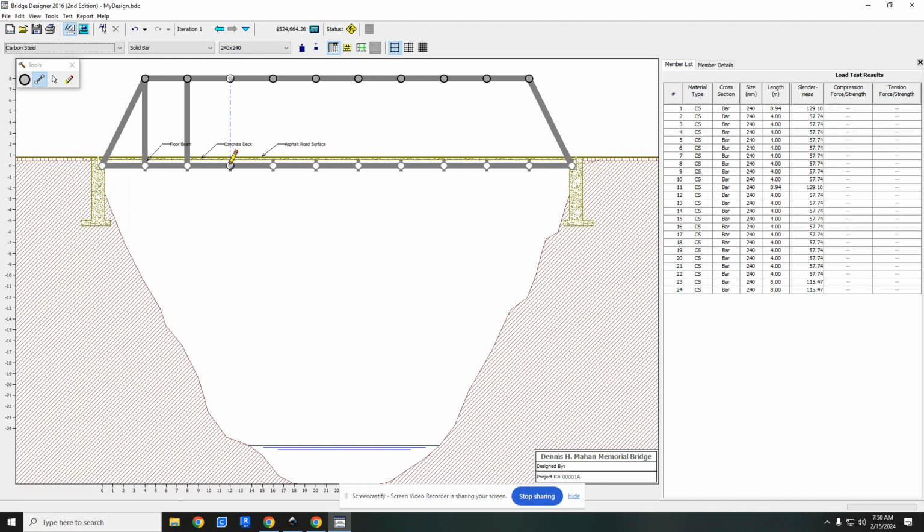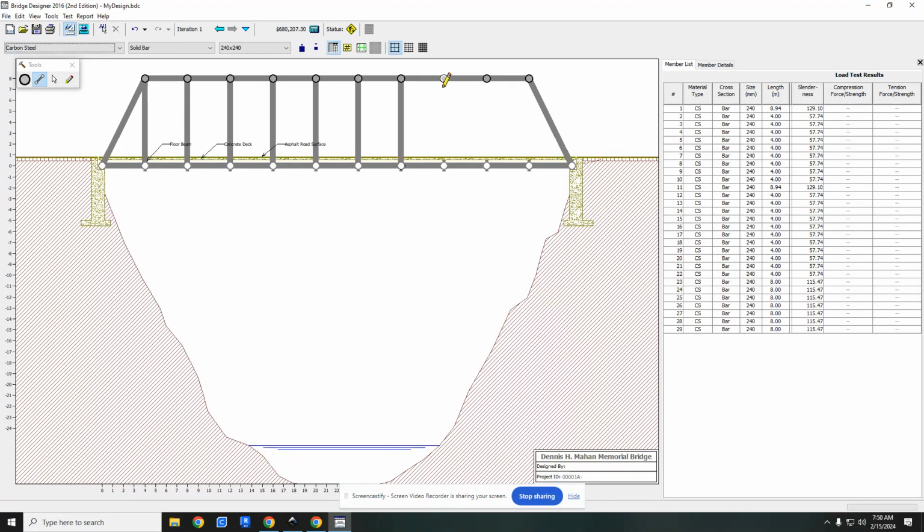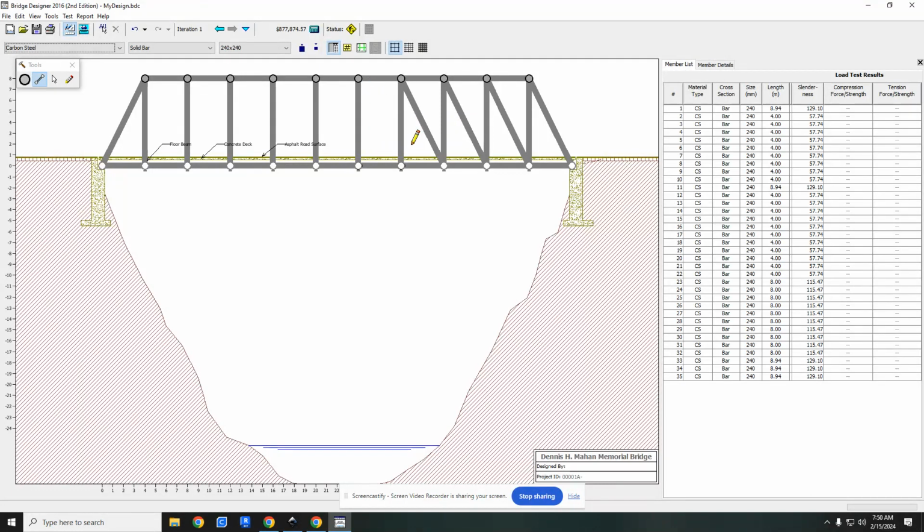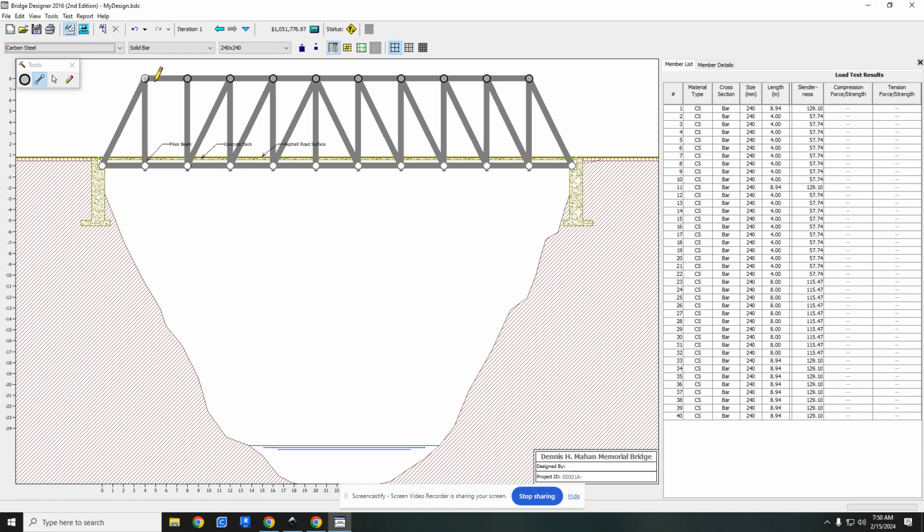Now, remember in the presentation that I have posted on bridge design, one of the key aspects of bridge design is we don't want rectangles. Rectangles are bad. Rectangles flex, right? We want triangles. So what you can do is, every time you have a rectangle, just add a diagonal member to it. And this is our middle one, so I'm just going to do both. Just add a diagonal member to it because remember, we like triangles. We do not like squares.